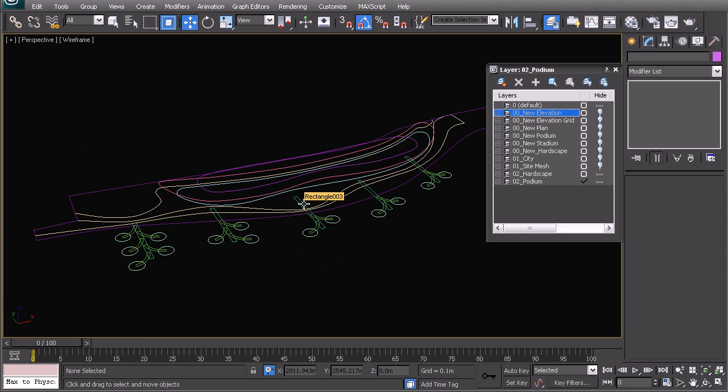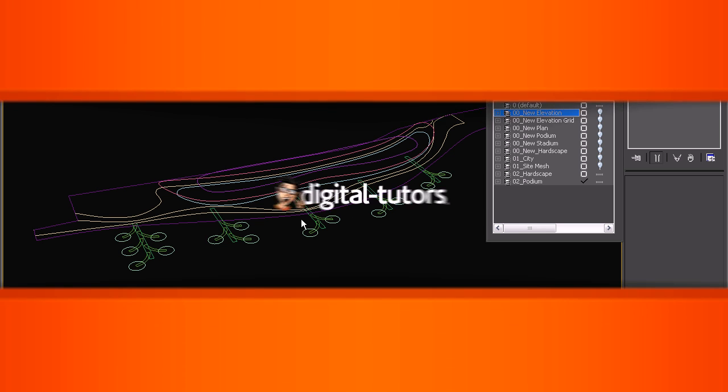These splines are going to be the reference that we will have for the slab edges. The balustrades will be made from them. All of the other objects in those regions will be generated from these initial splines. So they are very important to have in the right height and in the right position. And that is it for this video. We're looking forward to the actual extrusion process in the next one.